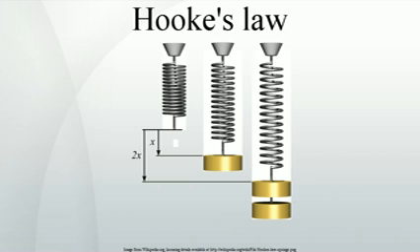Anisotropic materials. The symmetry of the Cauchy stress tensor and the generalized Hooke's law implies that. Similarly, the symmetry of the infinitesimal strain tensor implies that. These symmetries are called the minor symmetries of the stiffness tensor. This reduces the number of elastic constants from 81 to 36.